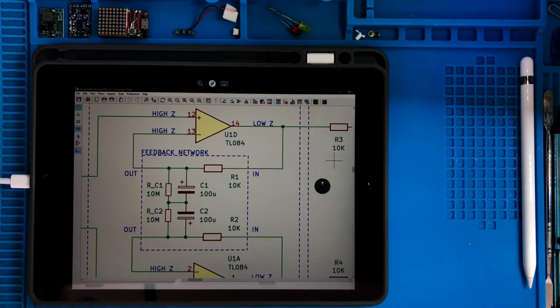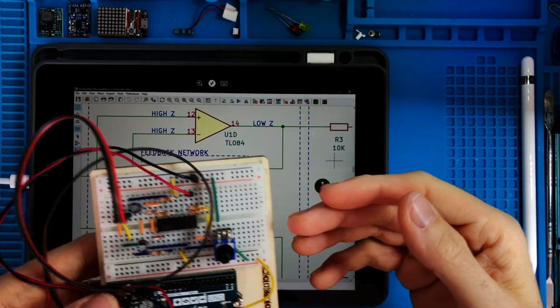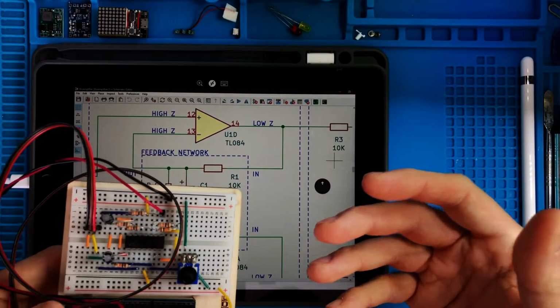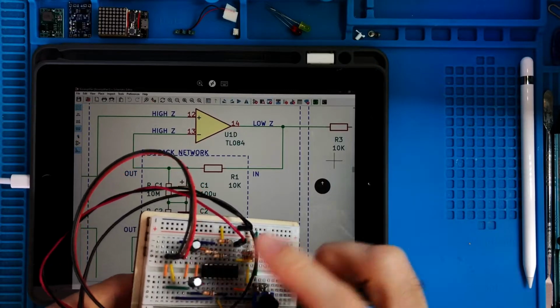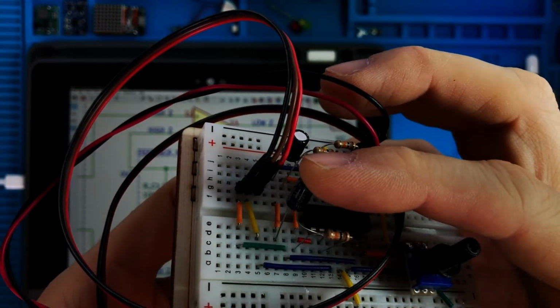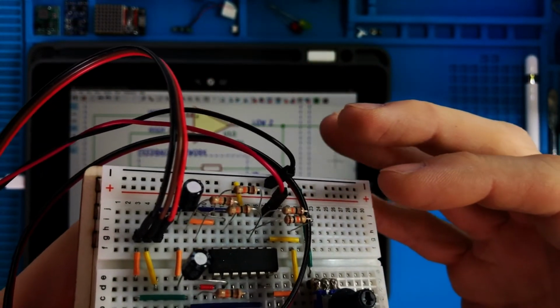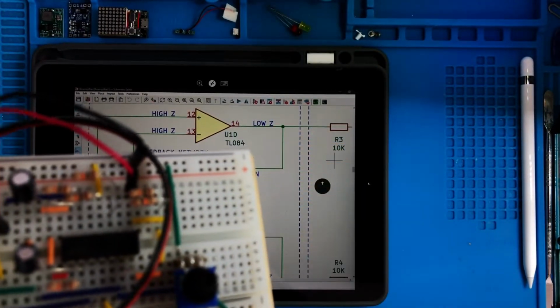Here we have the breadboard, and the breadboard also has a certain resistance that can be very high, in the order of the megaohms, maybe hundreds of megaohms, but not infinite. Also the capacitor itself is not a perfect ideal capacitor. It will have a certain internal resistance, which is something, now we don't know exactly what.